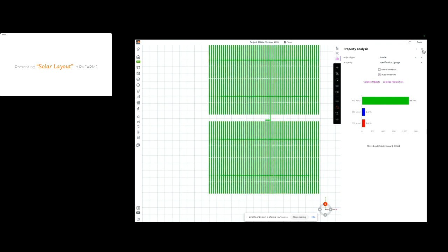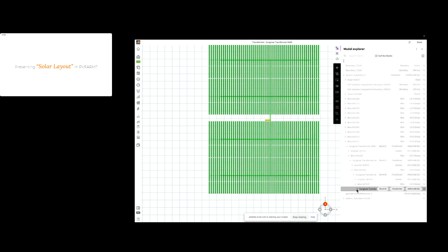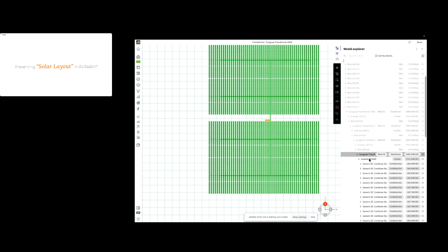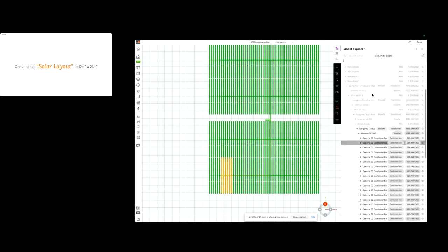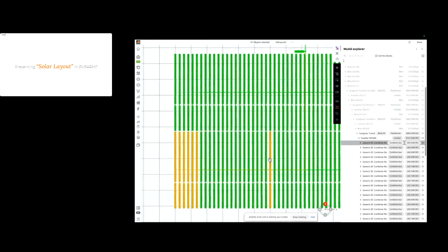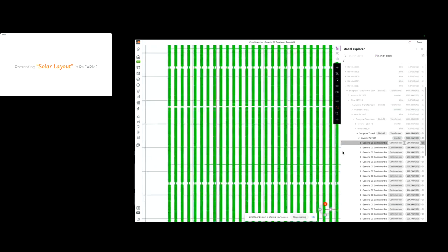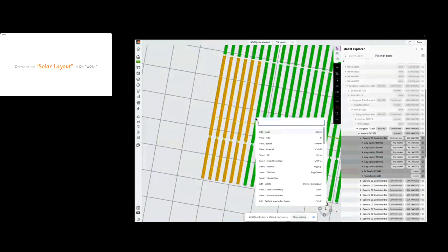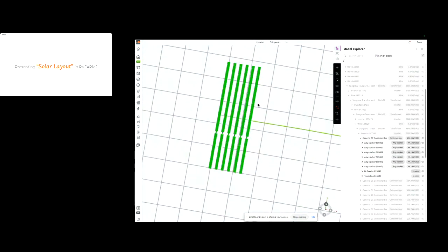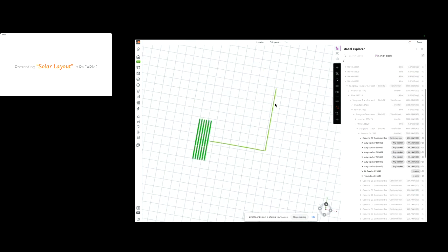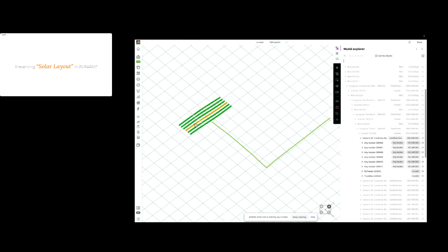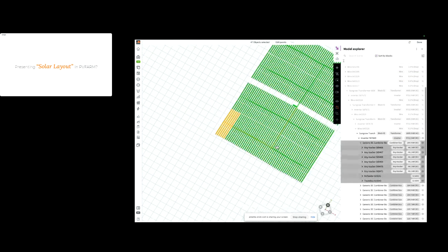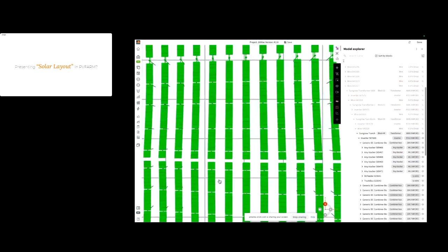However, what's important here is that in our hierarchy, if I select this particular block and dive in, you will see that the inverter connects to the transformer, and then there are a bunch of different combiner box circuits or combiner groups like this one. So for example, I can go to this combiner box, and if I isolate this group, you can see how those trackers are connected to inverters. They have extenders, then trunk bus, and then the DC feeder connects it to the inverter. So another level of detail, another layer of complexity.